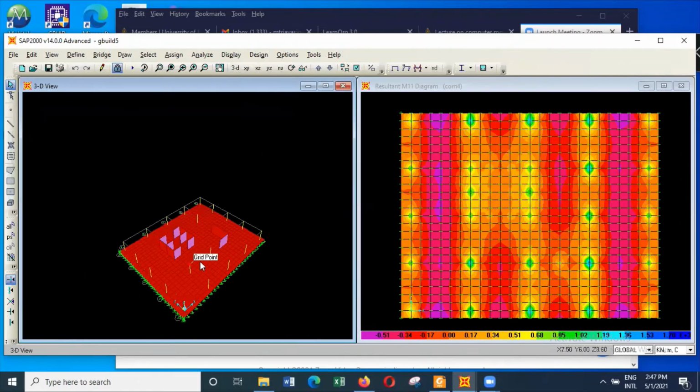So this is the area where you get a lot of shear walls, and that's the area you have fair distribution of forces. So here you can see the sagging moment does not rise as in these areas. So this purple color is one of the highest moments. So you can see the purple color high moment appearing in between columns, whereas the moments and forces in the projection area will remain low.